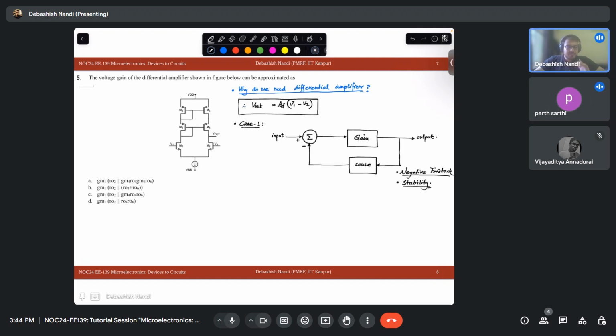Right. You want to fix the room temperature at 24 degrees centigrade. Now you switch on the AC, so the AC will start cooling. But can it exactly fix your temperature at 24 degrees Celsius? No. What it will do is first put your temperature at, let's say, 22. Then you feed it back to the loop and measure the error, that, oh no, my temperature has gone low. So it will automatically get this, this is your error. It will get the error signal and again feed it into the loop.